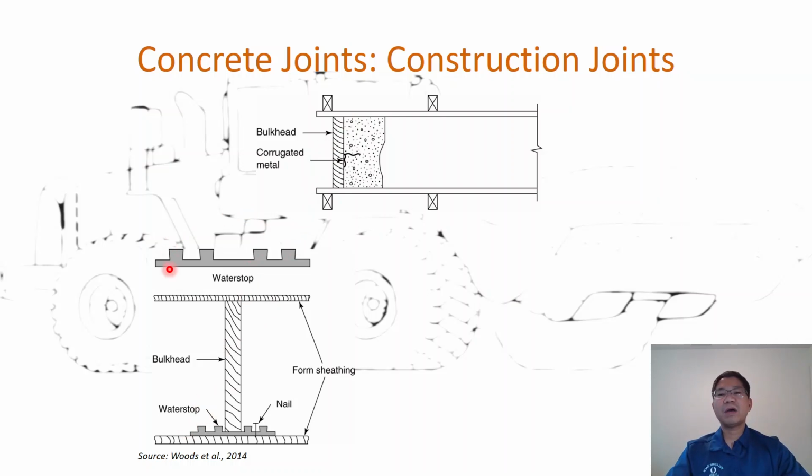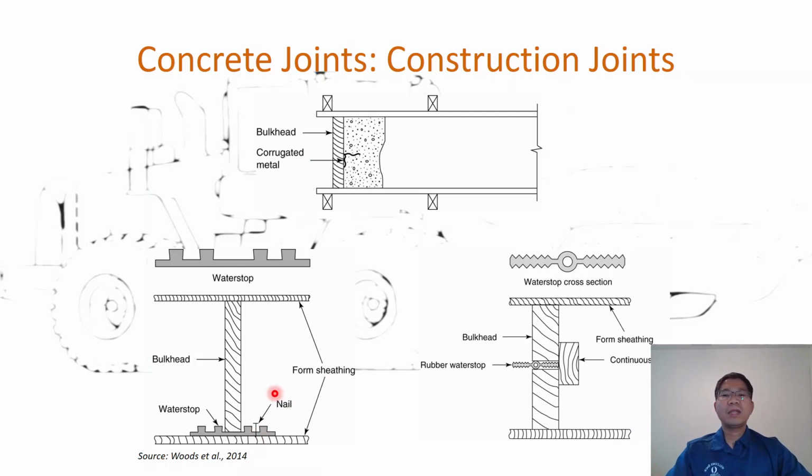The other is a water stop. It is made of PVC plastic, and you can see it there. So at the bulkhead, you see concrete on the left, concrete on the other side, and then as you can see, with that the water will not go through because of the PVC, and that's why they call it a water stop. It stops water from going through. Normally applied in water tanks, concrete, etc. And the water stop can also be placed in the middle, as you can see there.